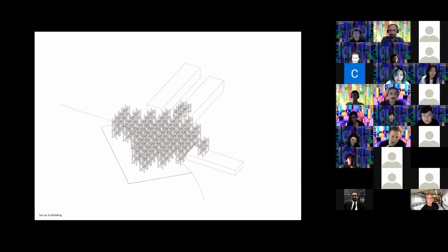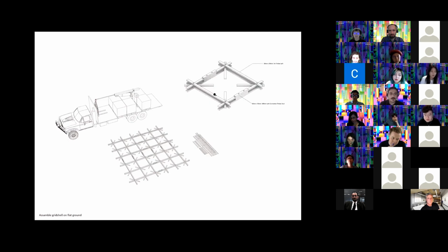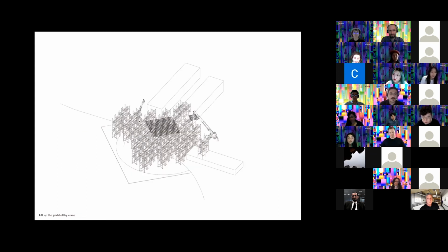For our project, the construction method used is called the east-down method. The first step is to set up the modular scaffolding prop-up system at the highest level, which is the peak of the designed grid shell. Gently lower the multi-prop jack to bend the edge down.